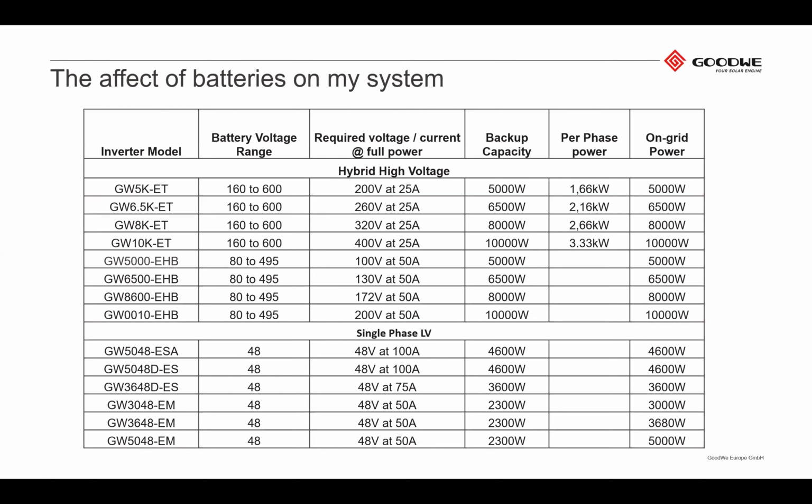Due to battery protection and not exceeding the battery discharge limits, the inverter overload time is a lot shorter, because it is reliant on one single source that doesn't have boundless energy. The overload time for just batteries on the ES series is about 2 seconds. Should they exceed the battery discharge limits for 2 seconds, it shuts down.